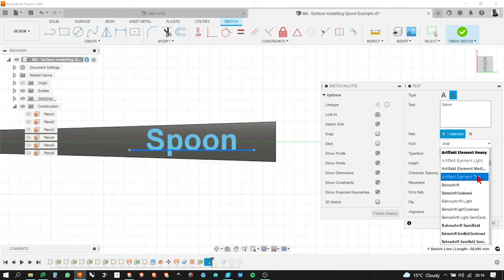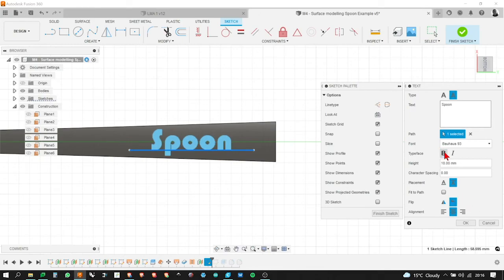And also, even some of the normal looking fonts, they come from a strange source. So they're not the standard Microsoft. I think you might need a TrueType font off the top of my head. There is a way around it. Let's just choose a font, any old font. Is that where using an SVG would be better? Possibly. I mean, the good thing about using native text in Fusion is that it's all editable. If you bring in an SVG and you want to change it, and you made a spelling mistake, you've got to bring it back in again. But yeah, I'll just choose any old font and see if it works, basically.